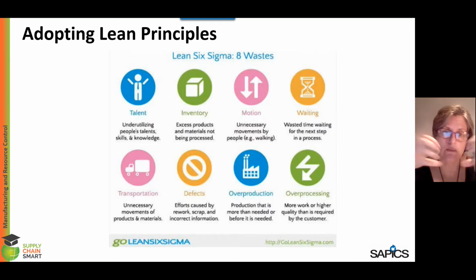In addition to the actual movement of material in terms of the cost of transport, is the cost of the defects. The defects are often caused by double handling in that transportation process, because the more times I handle a product, the more likely it is that I will damage it. Defects also occur in terms of the quality processes. So if your manufacturing process has quality issues where people are not paying correct attention, examples might be skew labels, incorrect dosing, under or overfill of product. These are all defects in your manufacturing process that can effectively cause rework.